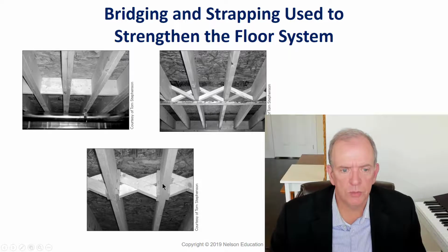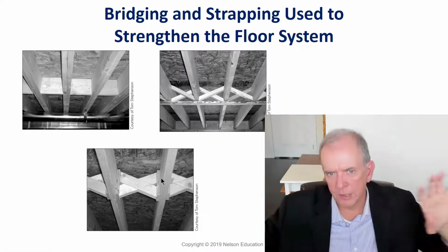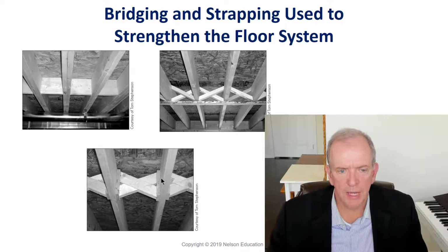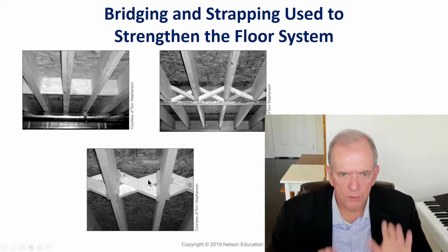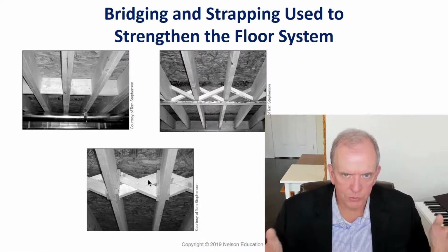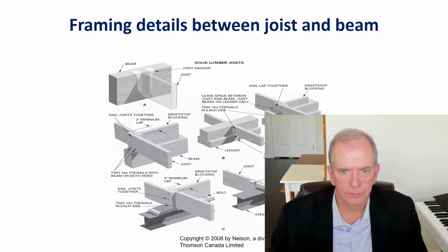And this is an engineered bridging, which actually you can, if you're trying to get the floor system to run a little bit longer and you get an engineer to review it and stamp it, then that would generally give you a little bit extra distance that perhaps you could get away with a 2x8 instead of going to a 2x10, or a 2x10 to a 2x12.